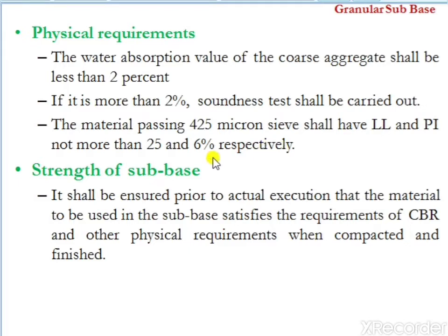Next is the strength of sub base. What is the strength of sub base and how is it determined? Let us see. It shall be ensured prior to actual execution that the material to be used in sub base satisfies the requirement of CBR and other physical requirements when compacted and finished.